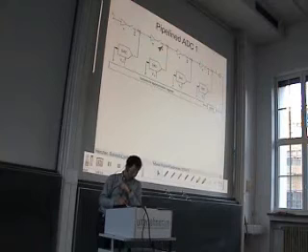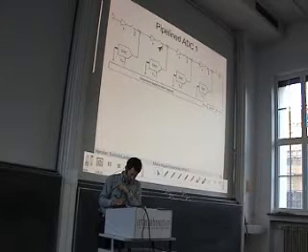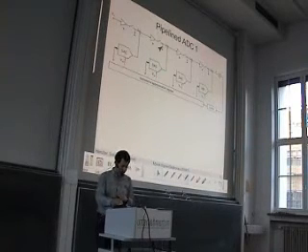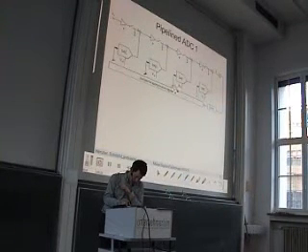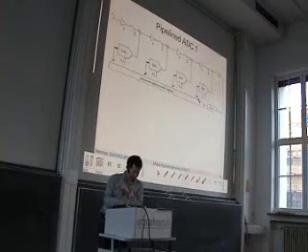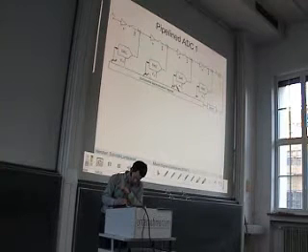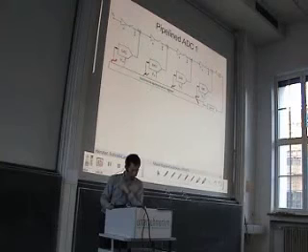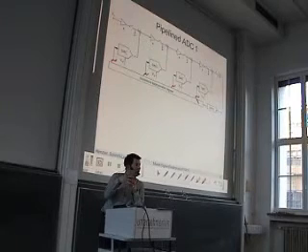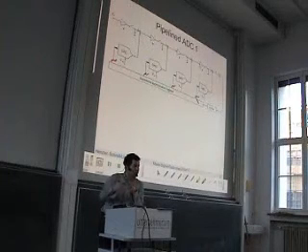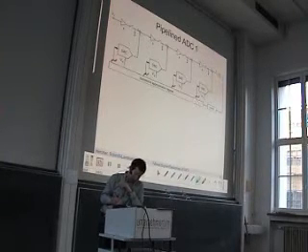So if we start from the original converter architecture, the first thing that we have to do is to break the feedback. So this does not mean a ground, this means that we break the feedback here, okay? Perhaps I draw it like this. So each stage is autonomous. We do not control all DACs by a global controller that is in a feedback loop, so we break the feedback. Then we have to insert these sampling elements.